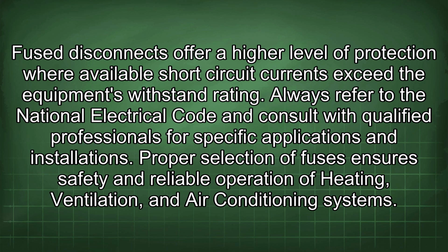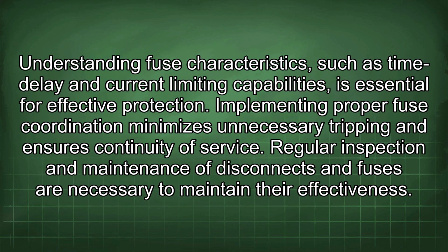Proper selection of fuses ensures safety and reliable operation of heating, ventilation, and air conditioning systems. Understanding fuse characteristics such as time delay and current limiting capabilities is essential for effective protection. Implementing proper fuse coordination minimizes unnecessary tripping and ensures continuity of service. Regular inspection and maintenance of disconnects and fuses are necessary to maintain their effectiveness.